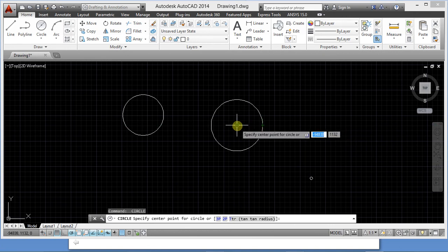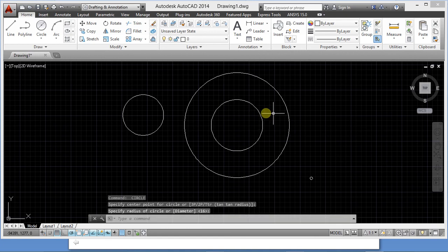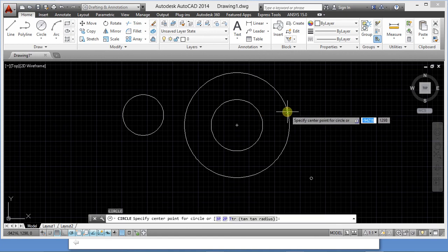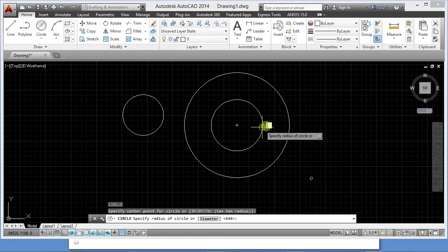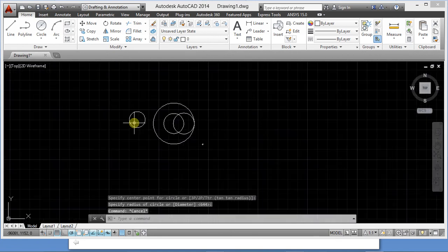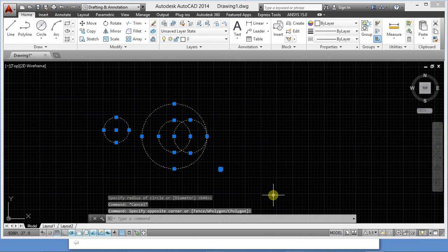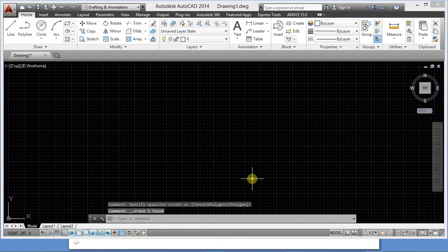Assuming I want to start sketching another circle inside there. I want to sketch as many circles as possible. Enter the circle. It now shows you the center, and now shows you the midpoint. Assuming I want to draw a circle from that midpoint, it shows you. You can use your middle mouse button to zoom. You can highlight and delete with the left mouse button selected.